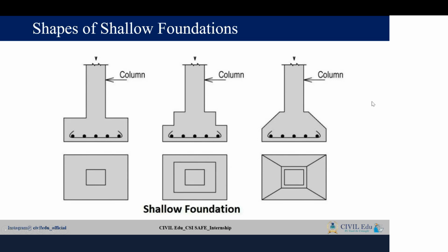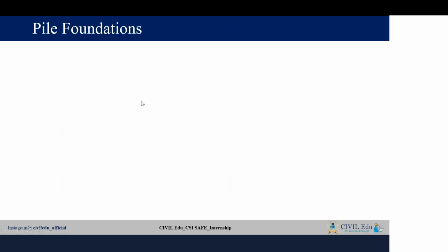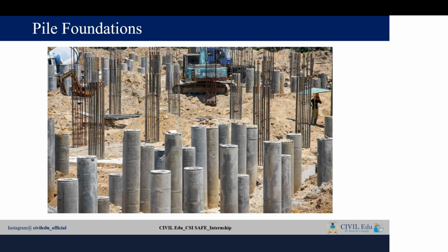These are the front views or elevation view, you can say. Okay, and then the pile foundations. Pile foundations come under the category of deep foundations. You can see these are all the pile foundations. You can see huge columns, not just small columns, they are very huge columns. These foundations are used especially when you are constructing large bridges, long span bridges. In those cases you are going to use the pile foundations.